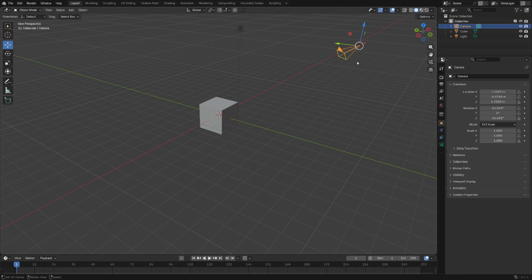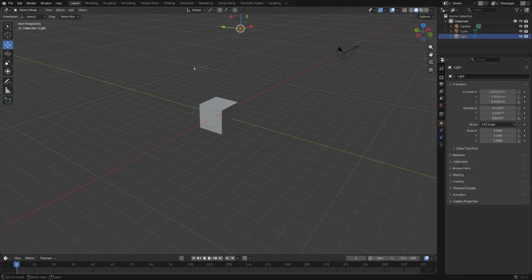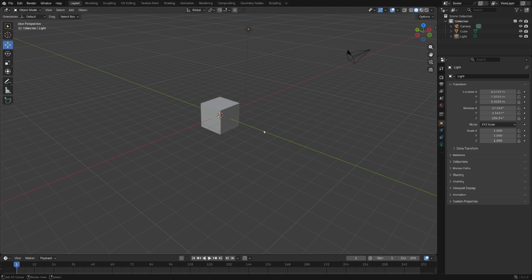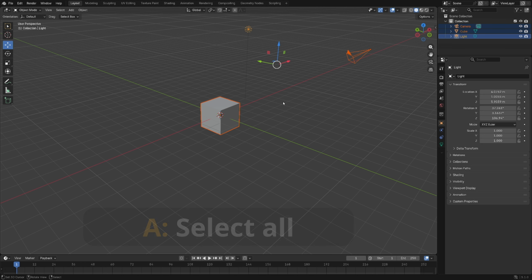First, using the click we assigned when it asked us. Here, I'm using right-click, but if you used left-click, use that one. If we want to select multiple objects, we simply drag with the click. And if we want to select all objects, we press the A key. To deselect them, we press the A key again, but in this case, it didn't let me, since by default, Blender requires double tapping A.